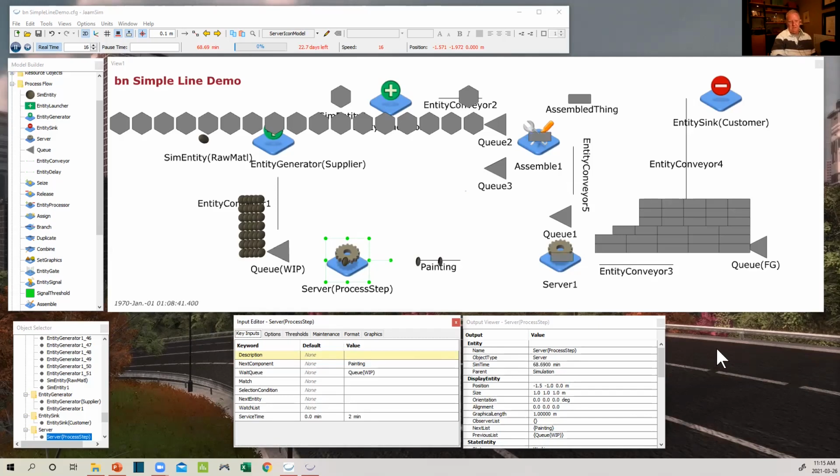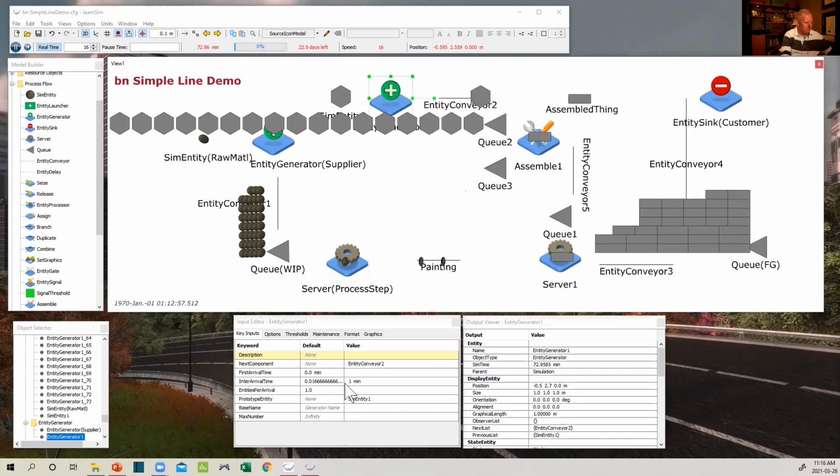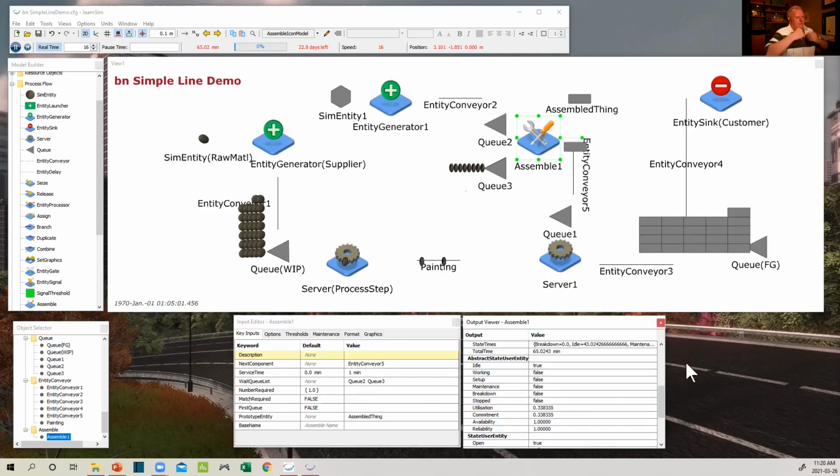Okay. So it doesn't look good that you have a bottleneck at Q3. Yeah, clearly. Well, and this is sort of the optimization that you have to do. Clearly, this guy is generating something far too quickly. I need to make this maybe every 3 minutes instead. Okay. Hey, my model looks a whole lot more balanced though, doesn't it? Yeah, it looks very good except for conveyor 2. Can you slow it down for half a second? Conveyor 2 needs to be slower.